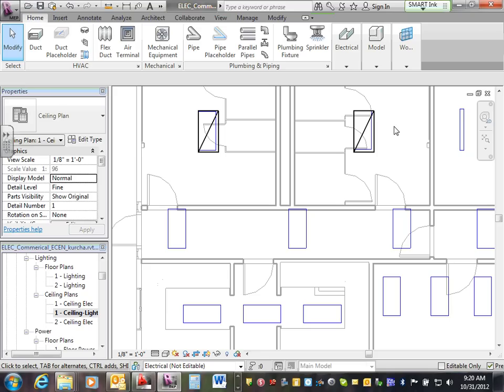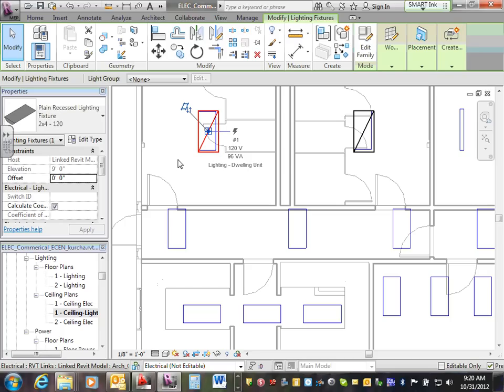Okay. Can I have thumbs up when you guys drop two, one at the top of each? Okay. I would like you to go click on the first one in the male's bathroom. Cool. And do you see elevation? What does the elevation say? 9 feet. We're good. If you didn't see 9 feet, gentlemen, you have just placed your fixture in the floor. 9 feet. Can I have thumbs up, chat?